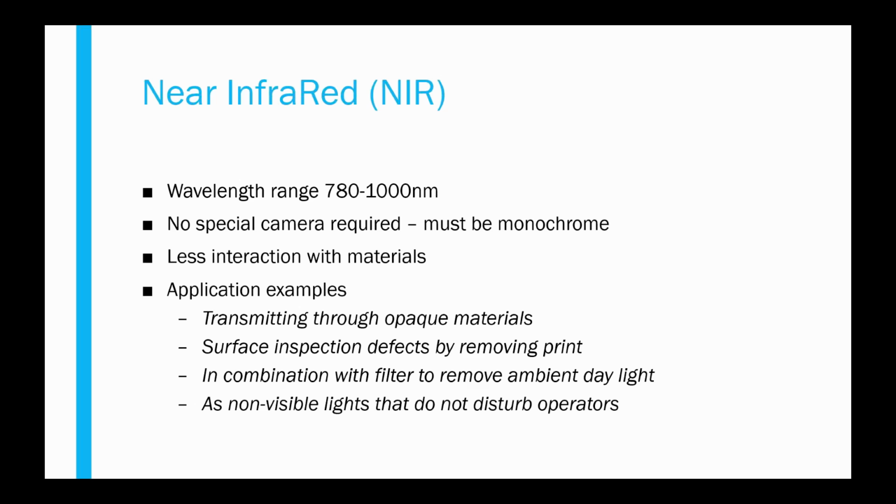This does not require a special camera. However, it must be a monochrome camera. And a lot of cameras have different spectral responses at different wavelengths. So if you do plan on using an IR light, it is a good thing just to confirm the spectral response of the camera you plan on using to make sure it has a decent response at that wavelength.